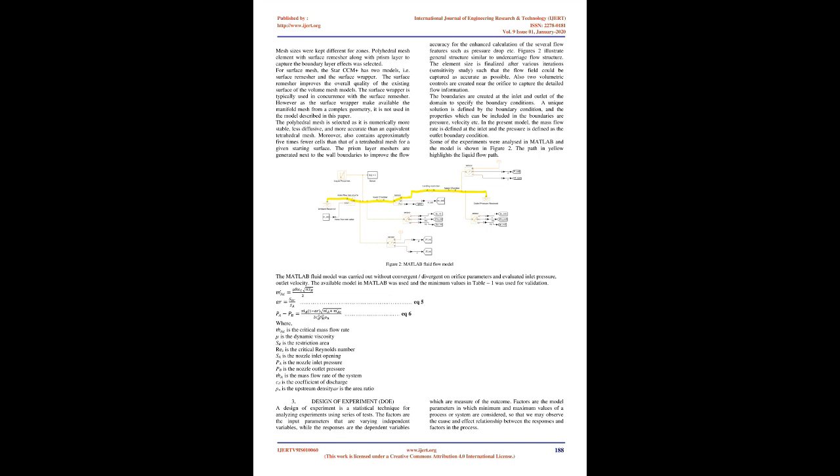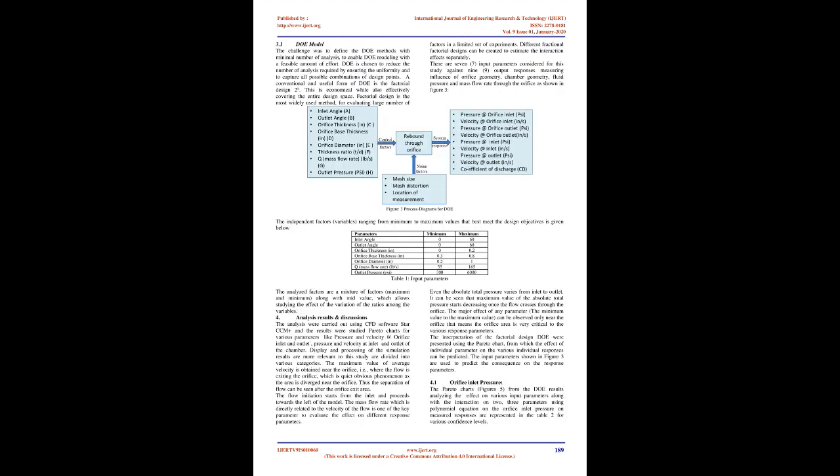The CFD analysis model was developed based on past experience using the following physics: 3-dimensional space, steady flow, oil, segregated flow, constant density, turbulent, and K-epsilon turbulence model. Refer to Figure 1 for the geometry details. Each turbulence model has strengths and weaknesses and is suited to a particular regime. The K-epsilon turbulence model is selected as it is robust, computationally cheap, offers good convergence, and is suitable for parametric studies, which is more relevant to the study discussed here.